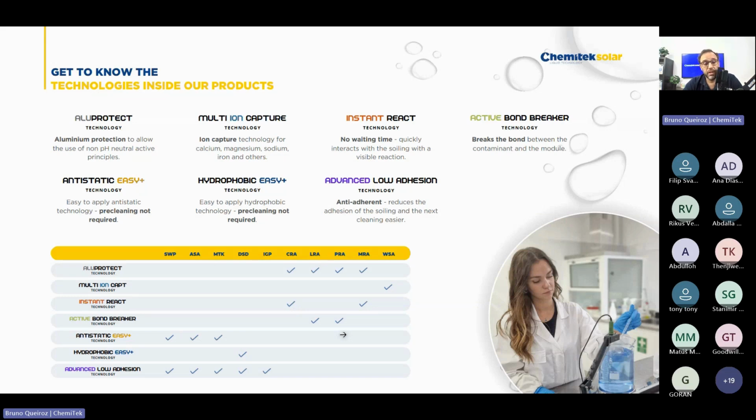You just clean normally as you would with the water or a cleaning agent, and at the end of the cleaning you will get the coating on the panel, because it's the brushing of the product against the panel that makes the coating adhere. Our coatings are water-based, they are not solvent-based or alcohol-based, so they need the mechanical action of the bristles against the surface to promote the adhesion of the coating to the surface itself.